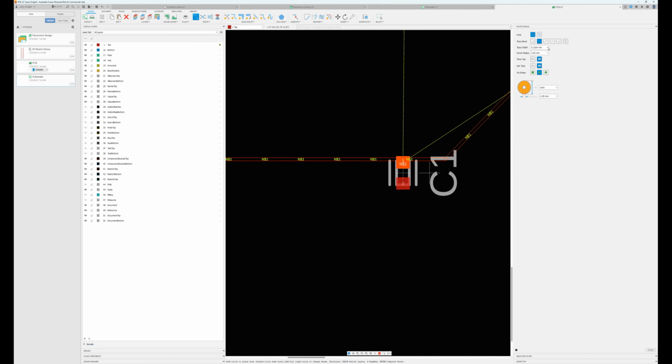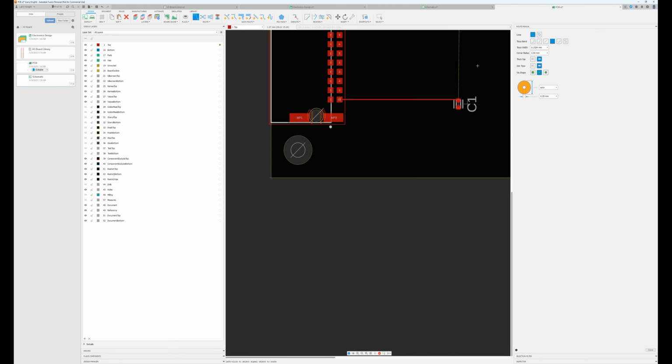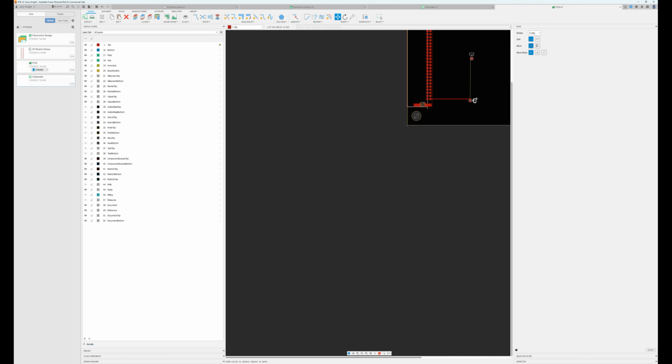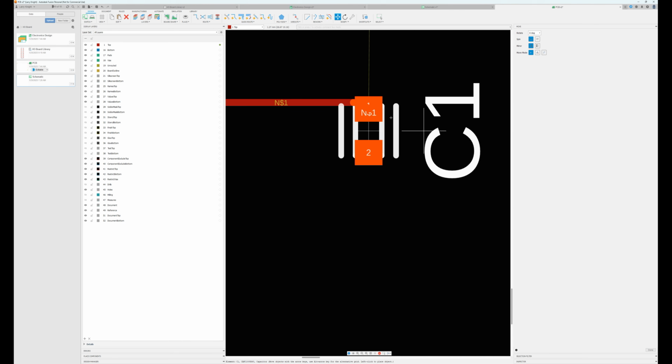And over here you can select if you want right angles, or curved. You can do a lot of different things, partially curved, and you can put it right on there, just like that. And then if you want to move your trace and straighten it out, you go back to move, and you can move the component to straighten it up.